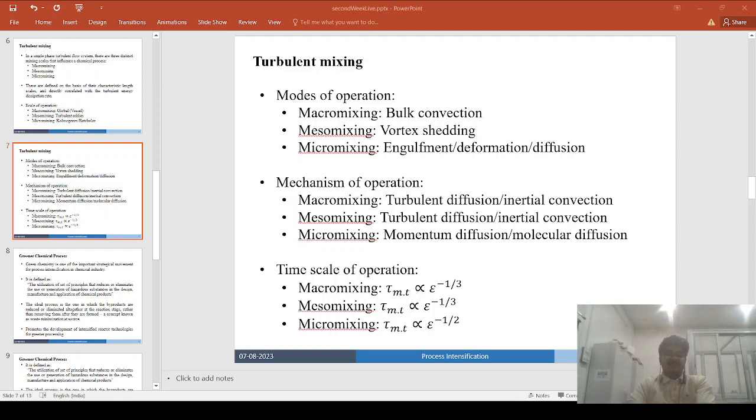So the macro mixing time in a mechanically stirred baffled tank is a function of the mean circulation time in the vessel. For a vessel configured for optimized mixing, the macro mixing time should be about 3 times the circulation time, and for a non-optimized system it is generally in the range of 5 times the mean circulation time. The mean circulation time is generally expressed in terms of the impeller pumping capacity, or QC.